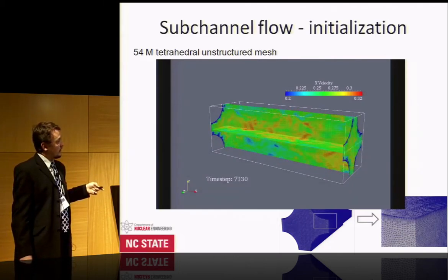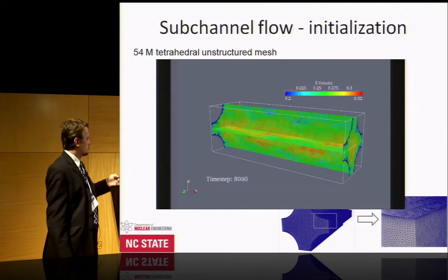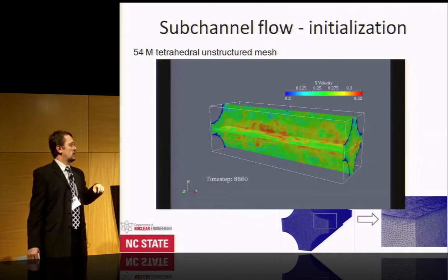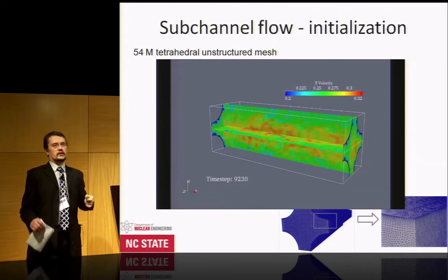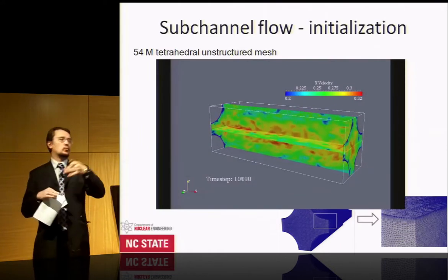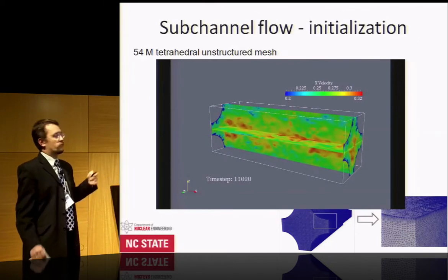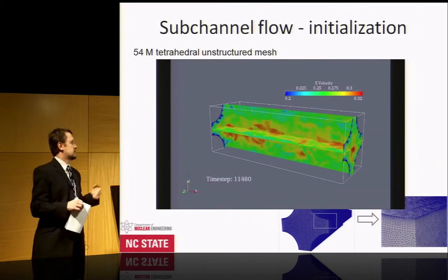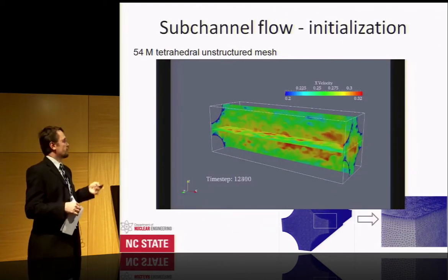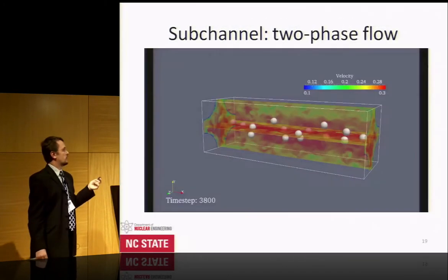This is just an example of the meshing tools and mesh results which we use. The movie shown here demonstrates how we generate turbulence by placing an obstacle and providing those wakes, and then we slow it down with the Courant number, so we fully resolve the turbulence. We don't want to waste time waiting for laminar flow to become turbulent while burning a 50 million mesh simulation at the same time.